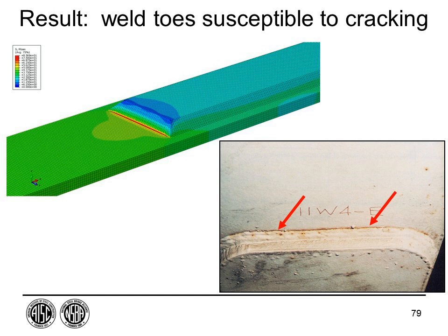So the research that was done on these back by John Fisher in the mid to late 1970s, even into the 80s, showed that there was really no difference in what you do at the end of the cover plate. In fact, even that end weld where the 2 little arrows are in the presentation, even if you eliminate this weld, it doesn't really make a difference. Now, there were slight improvements, and you can find that report from Lehigh, but it wasn't enough. When you remember there was a lot of scatter in the data, there wasn't enough to say that if I rounded these edges or made them square or tapered them, it was enough to worry about.